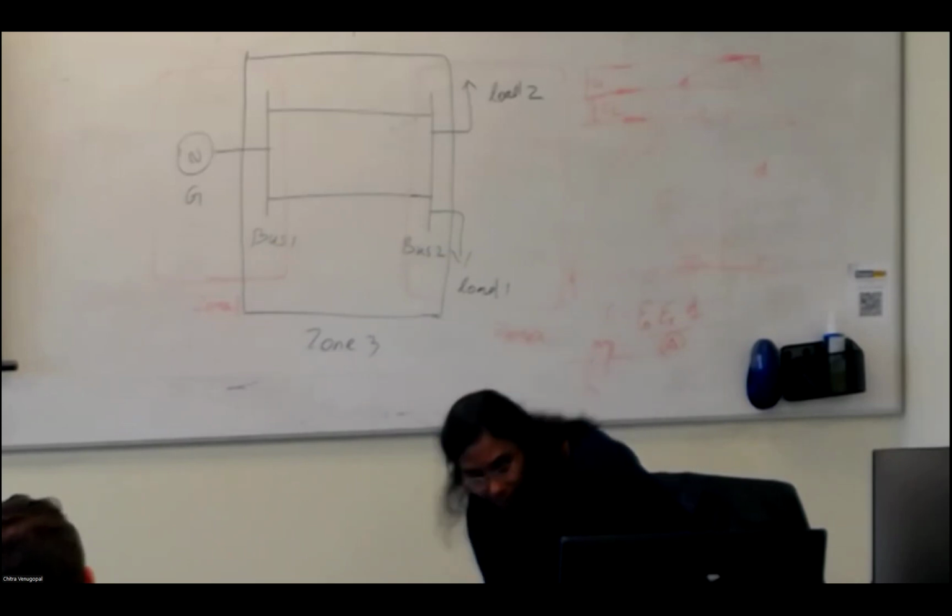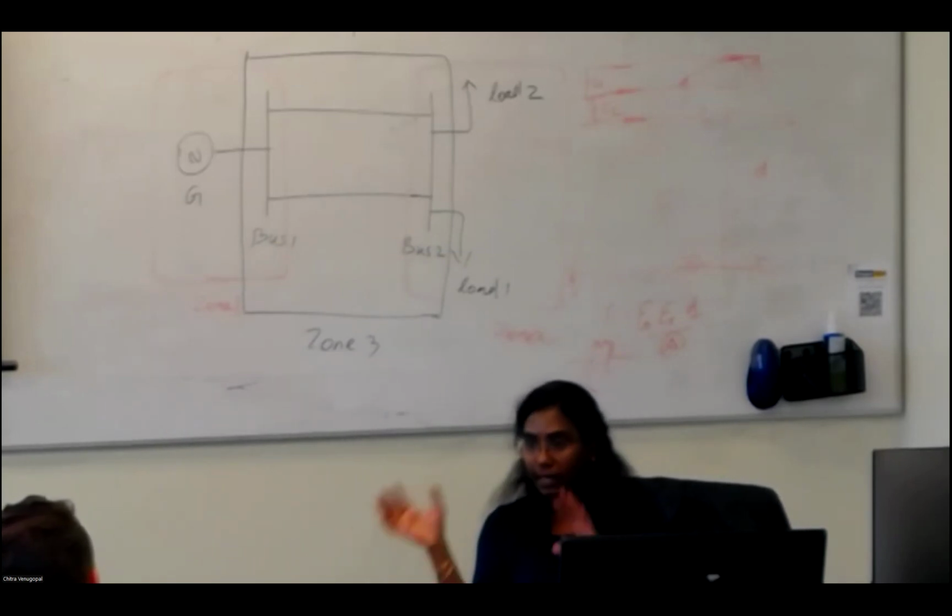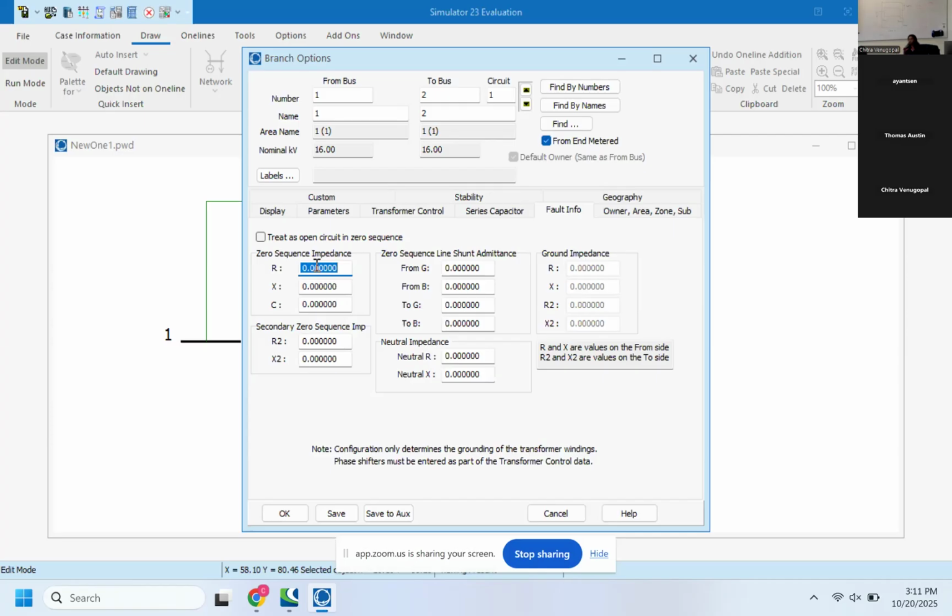Correct. Okay. So that is a zero sequence. Zero sequence indicates the ground. So it is very important to look at the ground values when you are talking about faults. We are not looking at the line to line capacitances. We are looking at the ground wire capacitance and the ground wire details, because they are contributing to the ground faults. Most of the faults, 70% of the faults, happen as single line to ground. Only one line will come to ground. Okay, so 70% of the faults.